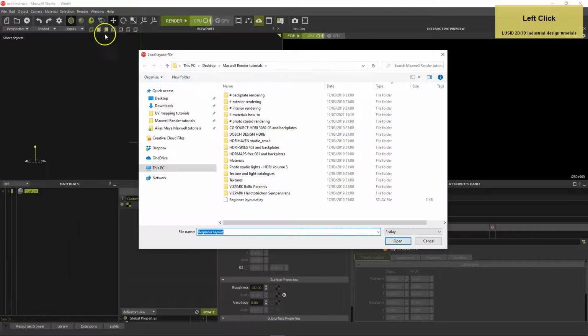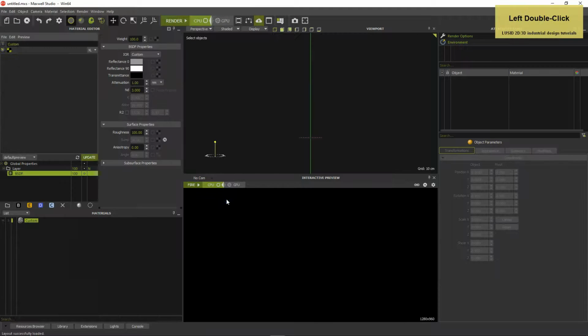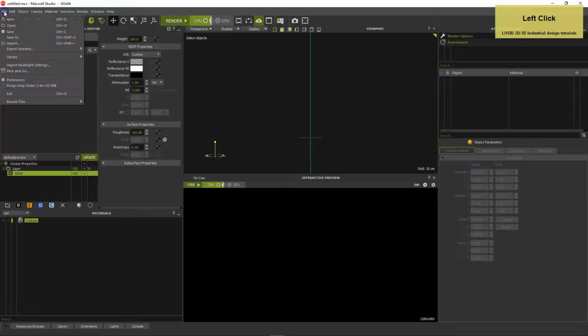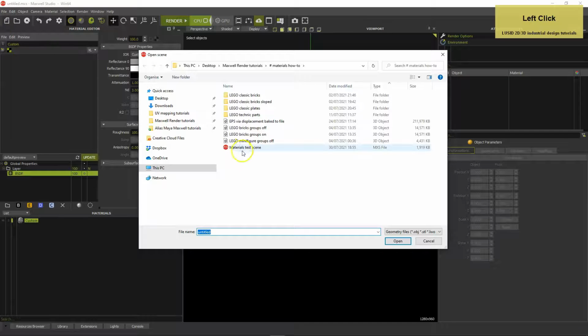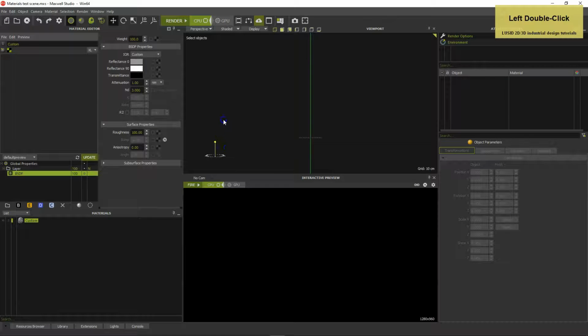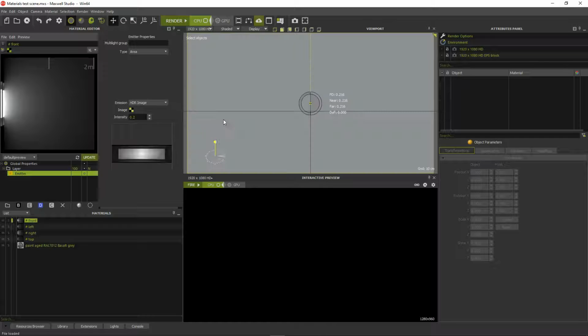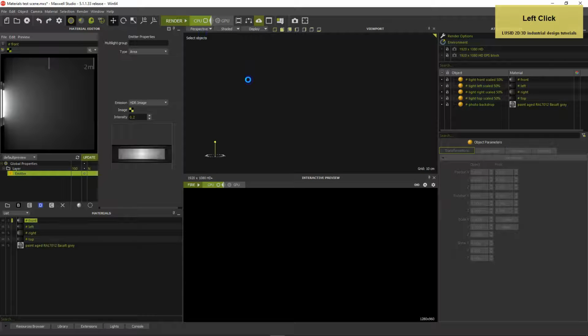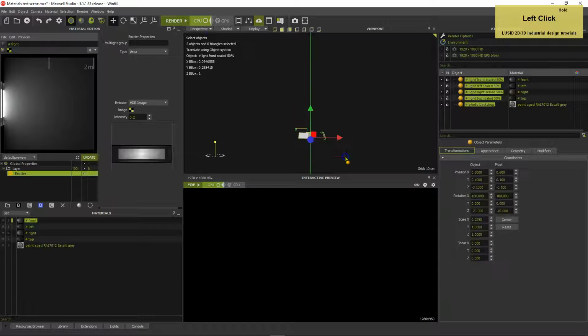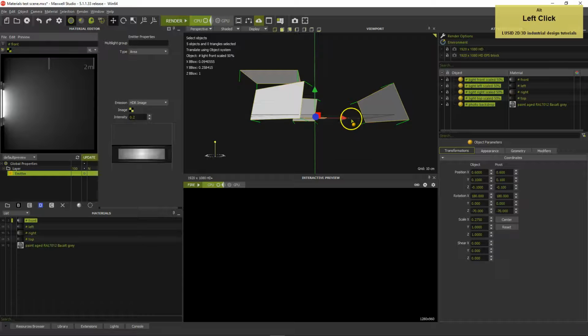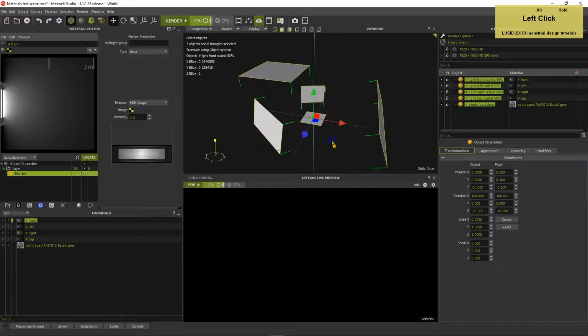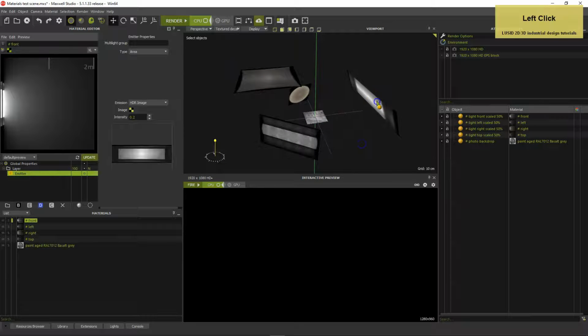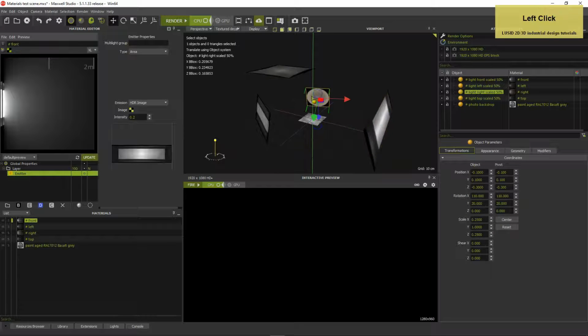Open Maxwell Studio and load a standard beginner layout using the Windows menu. Load the materials test scene and change the perspective viewport to textured decal mode, so you can see the photo studio lights and floor plane textures. This is a classic 4-point lighting setup that lets you appraise material properties rather well, provides reflections and allows you to create different photographic moods with multi-light without having to re-render.